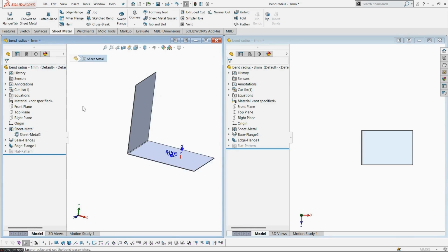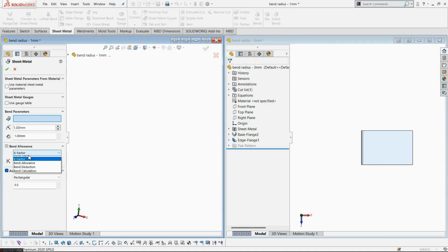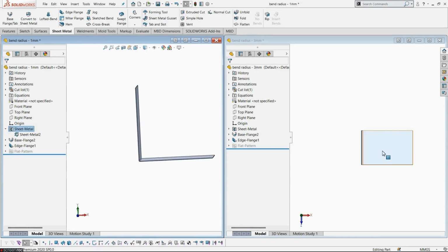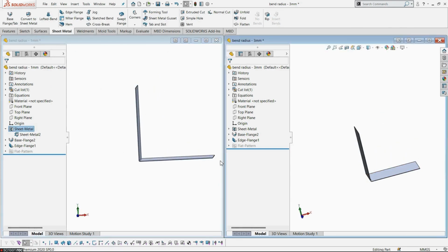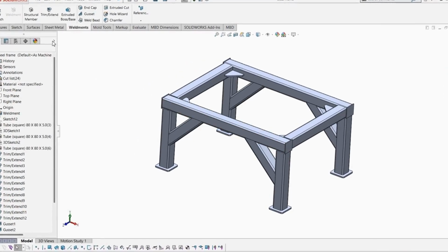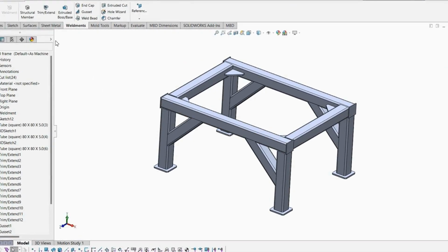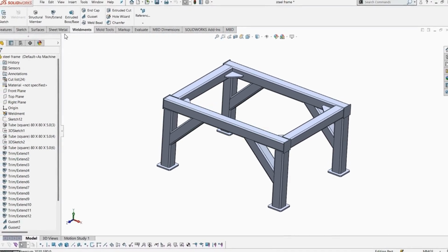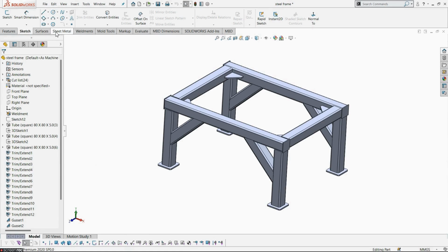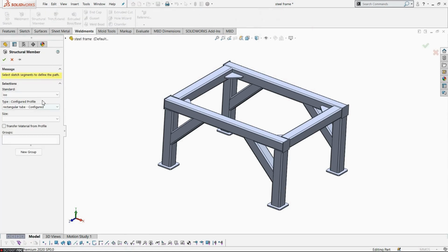In sheet metal, we need to clearly understand the types of cutting machines, K factor, bend allowance, bend deductions. All these important factors must be known while designing your sheet metal component, because they directly affect your cost. In sheet metal, we also learn how to use a weldment structure. Weldment structure is something we use in day-to-day life, like a terrace structure. If you want to hold any kind of part, like a table, we need to know weldment structure. Then only can we stiffen the part.